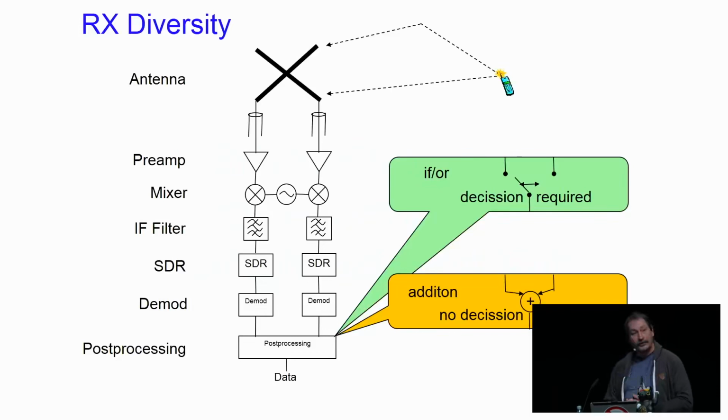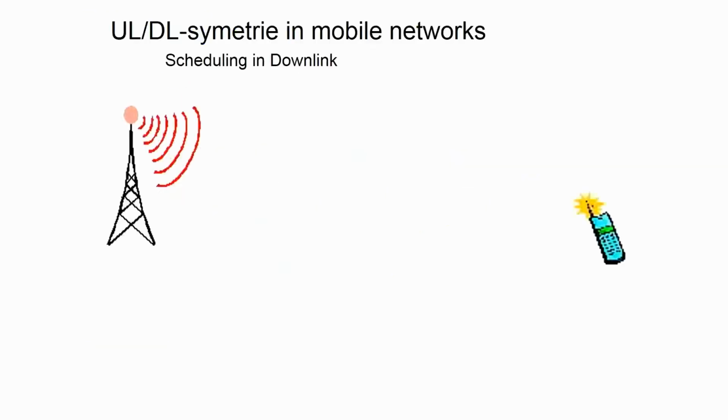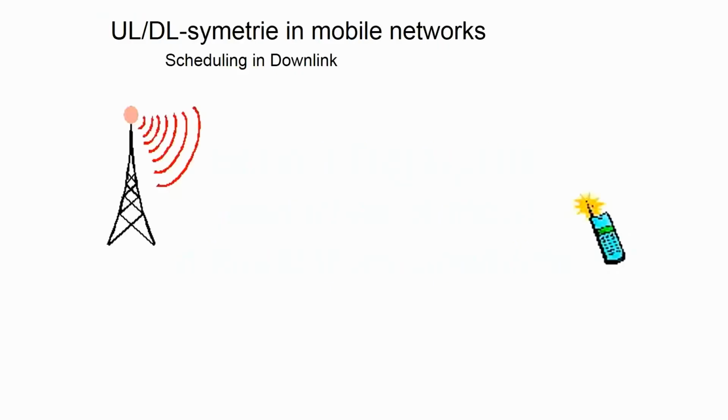And there's the other variant, so I can add the 2 antenna signals and use them together, so the total sensitivity is higher. But if one of the antennas has a problem or has some interference and the other is clean, then the entire cell doesn't work anymore. So it's a philosophical decision. One technician does it like that, and at other places it's done the other way. So the uplink has some other details, some tricks, if I may say so.